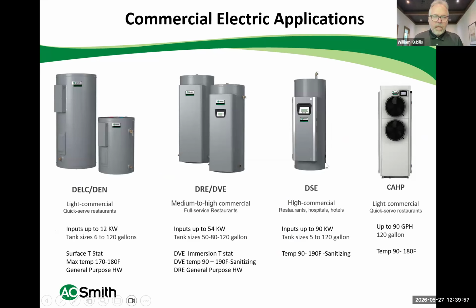The electric choices here, I don't want to dwell on this too much, but we do have quite a variety of electric water heaters, and they all have some reason and purpose. So, for example, our Dell and Den models are light duty units, but they only go up to 12 kilowatts. And 12 kilowatts is only going to heat just under 50 gallons of water an hour. So when you do need more than that, you do need to switch over to our DRE or DVE models.